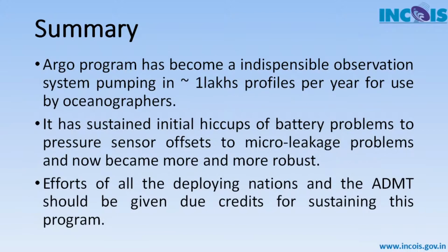There were a lot of problems in the beginning with battery problems, premature deaths of the floats, and also a huge problem with pressure sensor offsets due to micro leakages. And now it has become more and more robust. The life of each float has now been more than 4 years, and some floats have gone even up to 7 years.